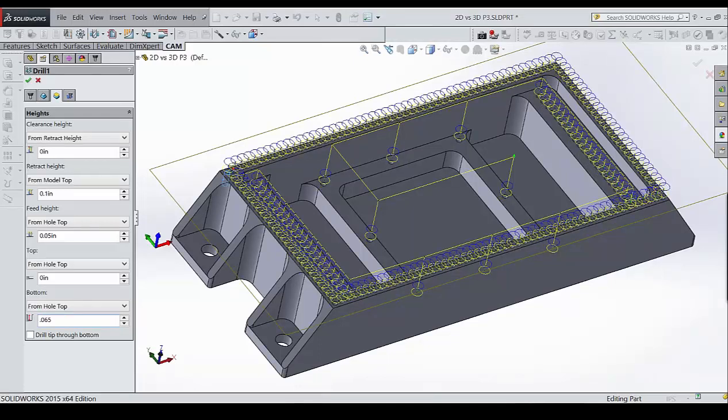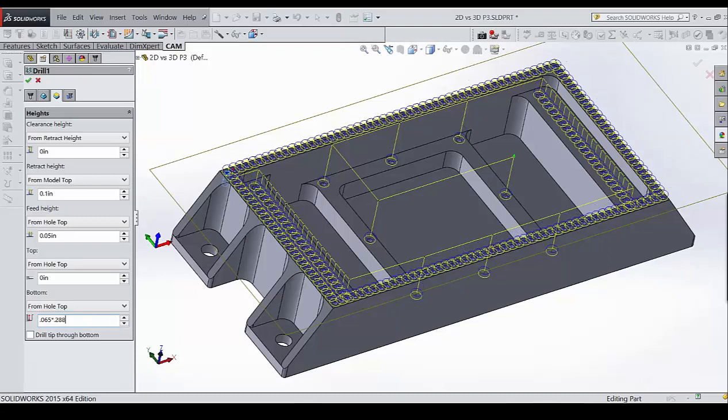and then it's a 120. I know that it's a 120-degree spot drill, so I'm going to multiply that by 0.288. It's a little formula I have written down. I think it's on page 27 if you have one of the little Haas shop notes books, if I remember right. I have some other notes scribbled on mine. But yeah, page 27 in your little Haas pocket notes. Obviously, if you multiply your diameter times 0.288, it'll give you the number you want.